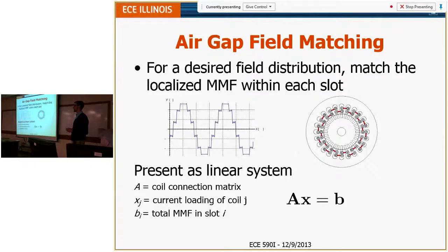Well, maybe I misunderstood what you said, but did I hear you say that you can dynamically reconfigure the winding configuration using a power source? Essentially, yes. If you have each one of these separate, so you have, let's say, a DC voltage coming in, and then an H-bridge, which can be either positive VDC, 0, or negative VDC, then you are putting whatever current or voltage you want in each one of these separately.